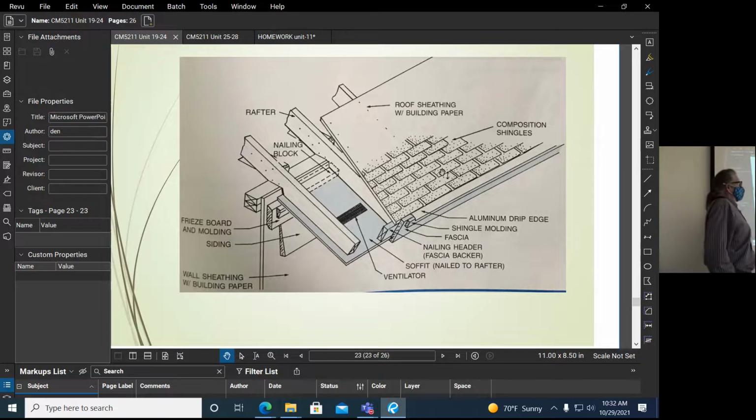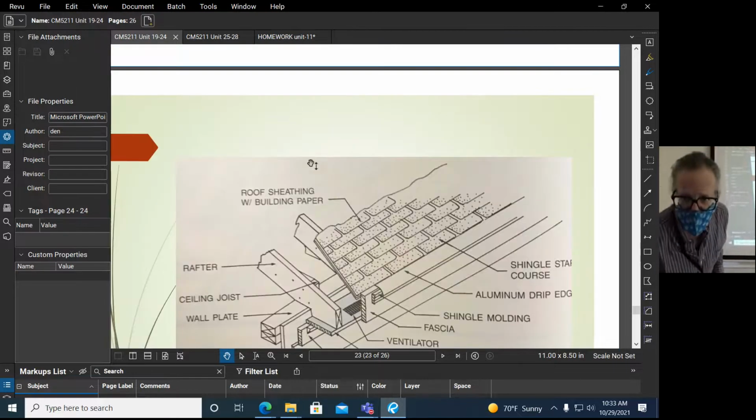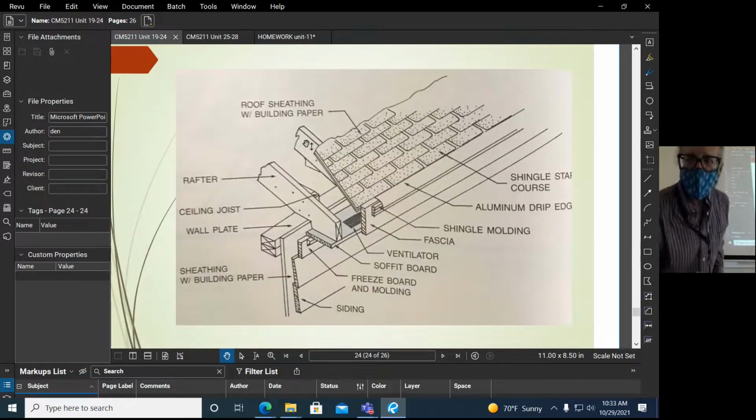Another way to do the soffit is just straight down with a piece of plywood, right? It's a lot simpler, just straight down the rafter instead of building out a box, which would go something like this. It's just another condition that's pretty common. You could even also, they do this a lot in California, just leave this open, and then you ventilate your roof structure from this plane here. So there's a lot of different ways you can detail the edge of the roof.